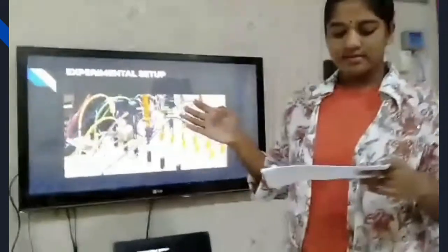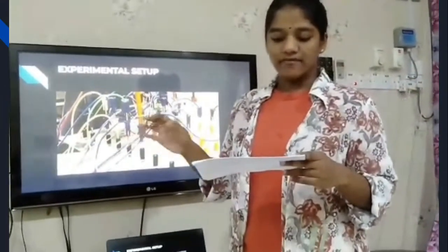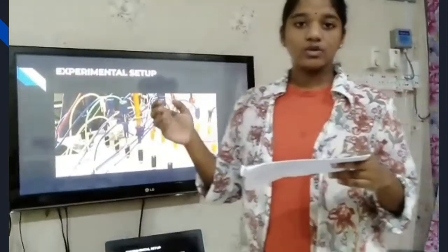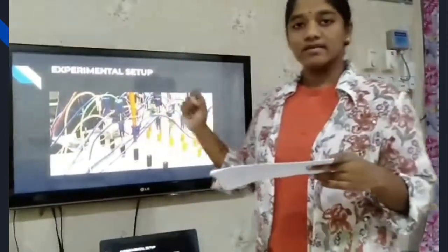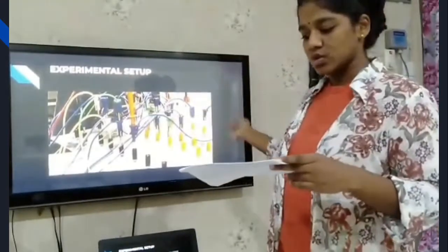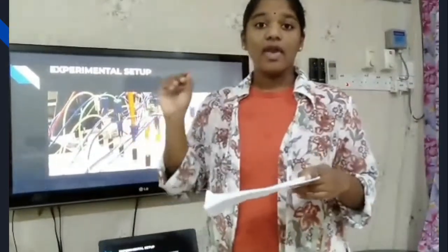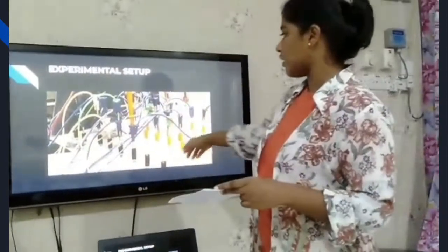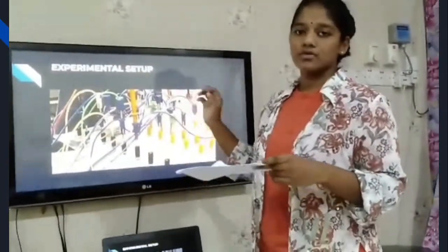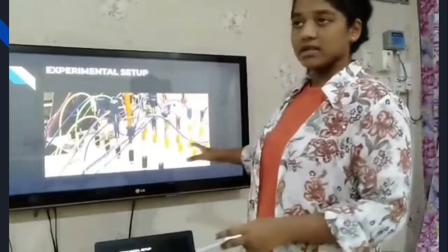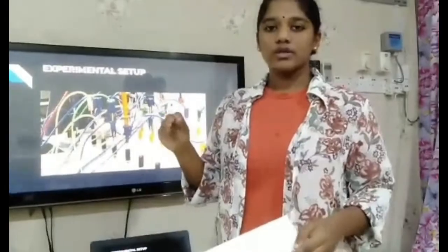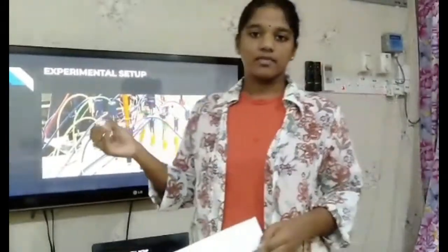In steady state, in no load condition, every capacitor acts as a smoothing column where it is charged to the maximum voltage. The maximum output voltage is 2nVmax, where n refers to the number of stages. Since we have 5 stages, n will be equal to 5. So this is all about the experimental setup. Later on, there will be a video included in the experimental setup.